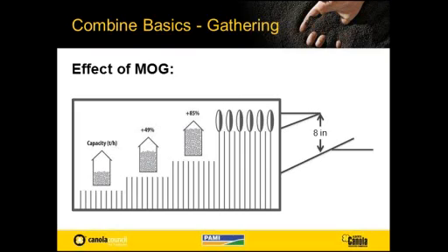Now, this isn't going to be exact for all crops, and some you're often limited to how high you can cut by the amount of stubble required to hold the swath up, or just getting below the pods may limit how much you can leave attached to the ground. So what you find, though, is that people need to understand that where the crop is very tall and you're putting a lot more straw through, you're going to have to deal with reduced capacity of that combine. And if it's short and mostly seed and grain, your grain capacity can go up dramatically.